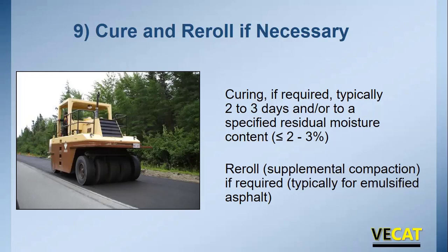This is usually not a problem with cold central plant mixes, and it's not a problem with foam mixes, as the foam tends to cure fairly quickly. But occasionally we'll see instances where after 3 to 4 to 5 days you still haven't dropped below 3%. And what we generally recommend, if you haven't dropped below about 3% in about 10 days, if it hadn't rained in a couple of days, you need to go ahead and cover it up.